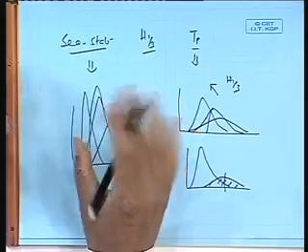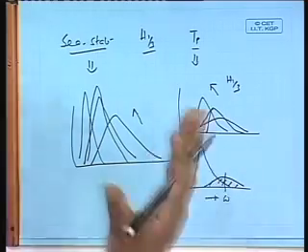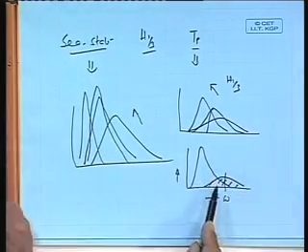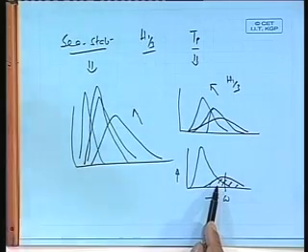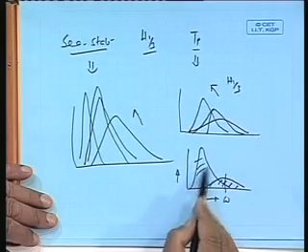See, when there is a 2 meter wave, it is all connected. I have got a wind blowing at 10 knots. 10 knots will give me a number of small length waves, 50, 100 meter long waves with a smaller height. So average height is less. So the spectrum is shifted on the higher frequency side, small wavelength side. As wind begins to blow more, I will have higher waves, also longer waves. So it will shift on this side and the area will also become more.